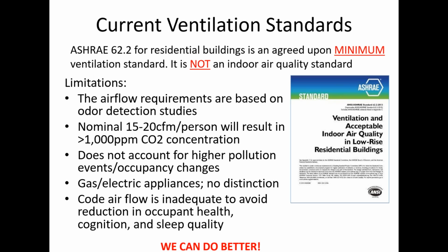So smart ventilation is going beyond current ventilation standards. A lot of you have probably heard of ASHRAE 62.2. This is the residential building standard. An important note on ASHRAE 62.2 is that it's a minimum ventilation standard, but it's not an indoor air quality standard by any means. It has several limitations, including the requirements are based on historic odor detection studies, so not actual air quality metrics. It leads to a nominal airflow rate of about 15 to 20 CFM per person, which will result in greater